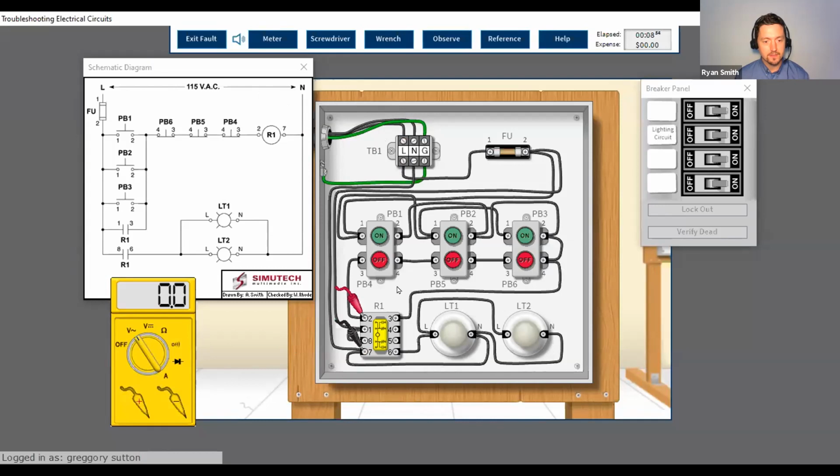Yeah, we learned that last time that if we get a 0 voltage across something that should have a full voltage, that means something might be wrong with that neutral potentially. Except, how do we have to get that voltage? Oh, right. I got a false 0 because I'm not pressing the button yet. So let me press the button. Okay, here we go. Yeah, let me try this other one here and see if it does anything different. Aha, I do have a full voltage across that coil.